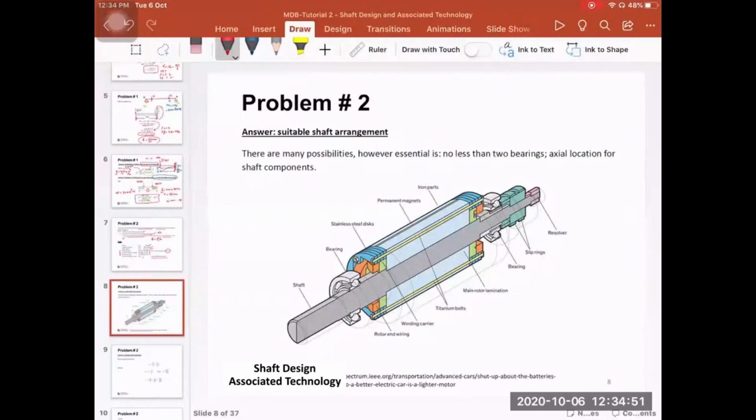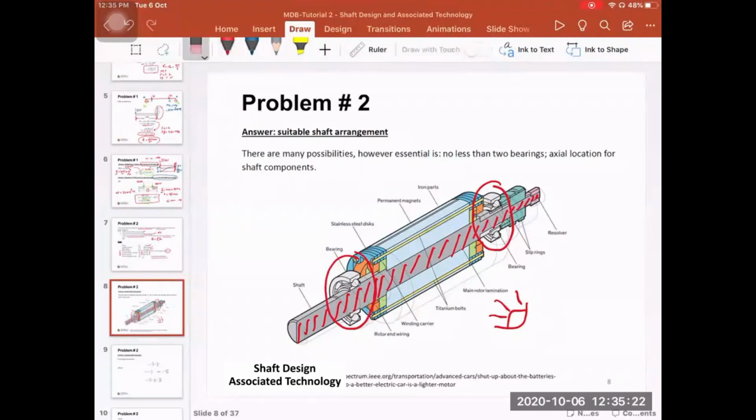And it seems complicated, but what you need to focus on is this gray portion in the middle, which is the shaft. Okay, so this is the shaft of this motor. Then you can even draw a view when you look from here. Then you see you have a bearing on the left hand side, and on the right hand side another bearing. And what is interesting as well is the snap rings.